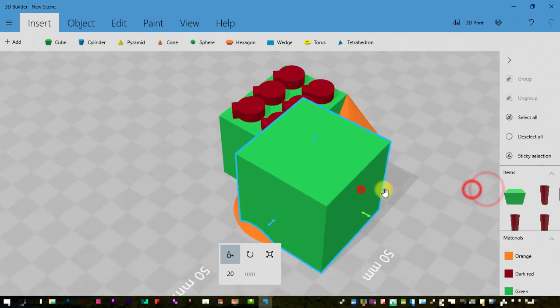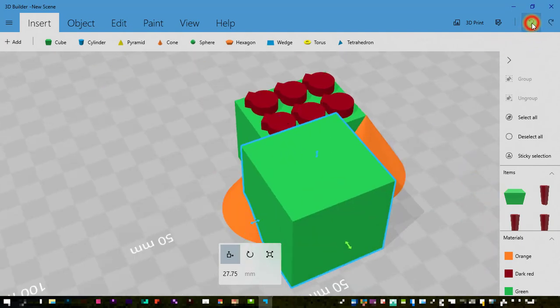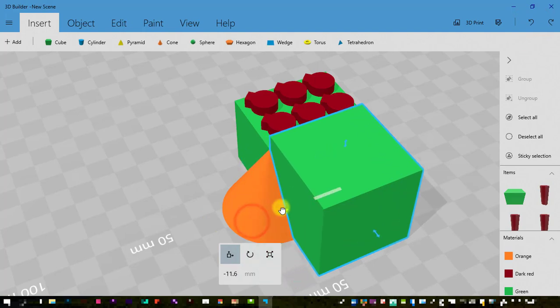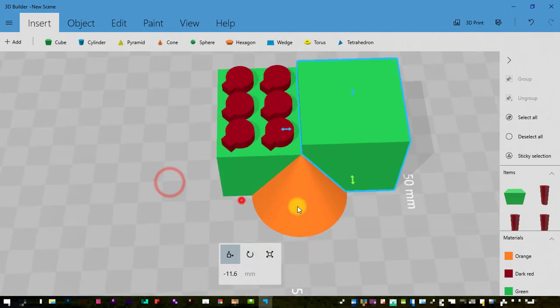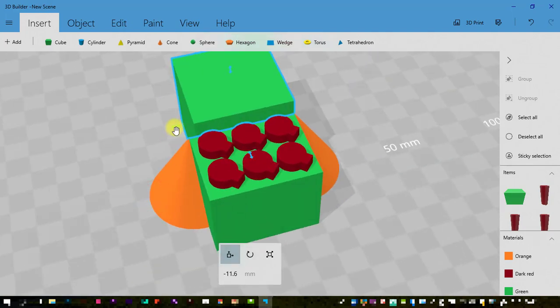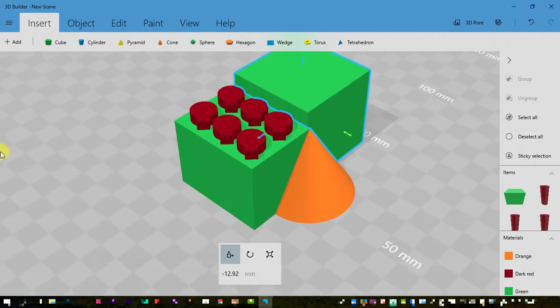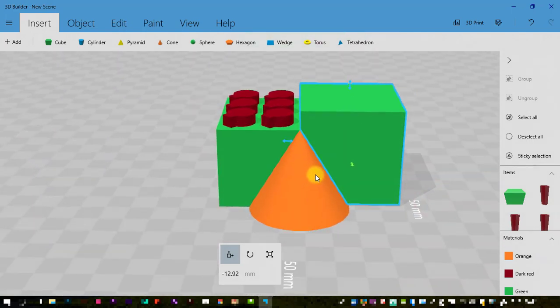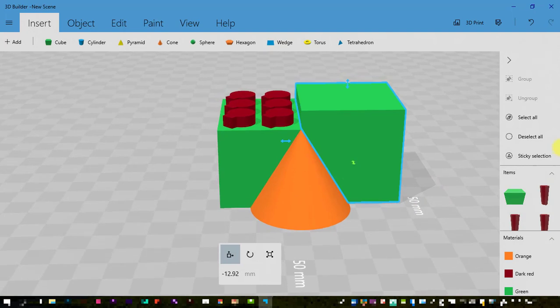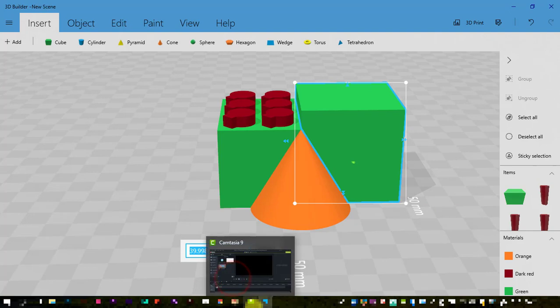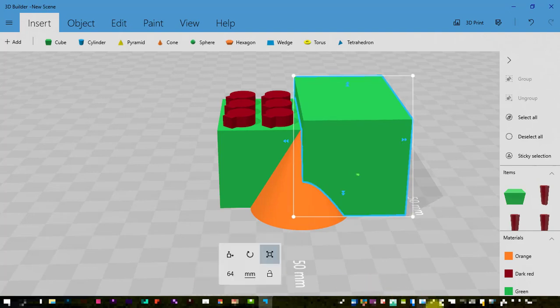I'm bringing in another cube now. This is going to form the holder for the little pieces of card. Now the cards I know are going to be 2.5 inches by 3.5. So I'll need to set this up so that it's exactly the dimensions that I want it to be. So I'm just locking that in place on the back of the pen pot. Having measured and then converted into millimeters, because I'm working in millimeters, you can basically go ahead and change that, or I did anyway.